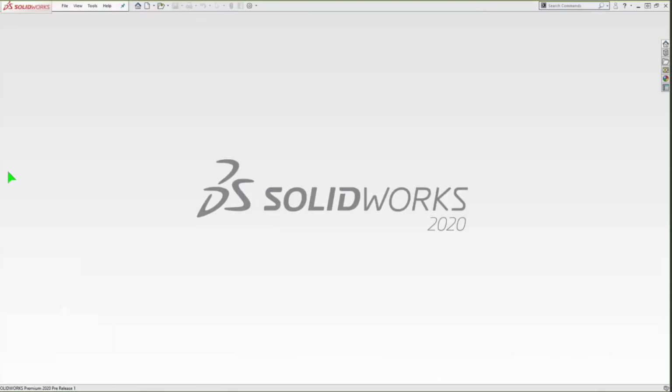Okay, so now the next option we're going to use is BREP mapping without entity check. So BREP is boundary representation. What it does is it changes the way that SOLIDWORKS is going to process the model information during the import. So it's going to try to use boundary representation to directly map the topologies as it imports this data. So generally this is going to be faster than the previous option we had that was knitting the surfaces, especially for your more complex models.